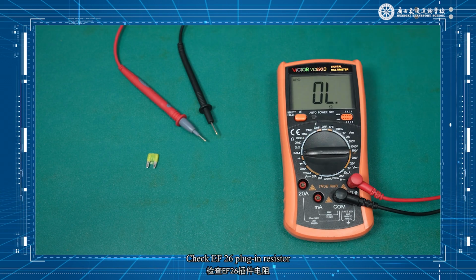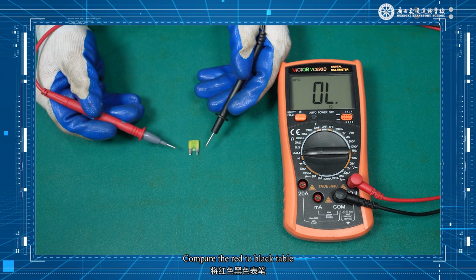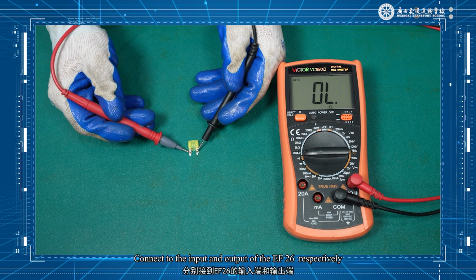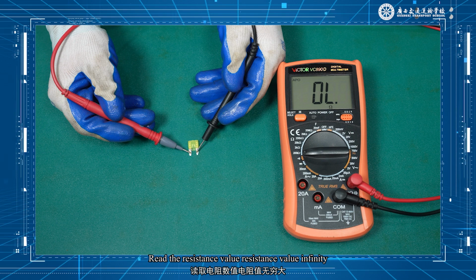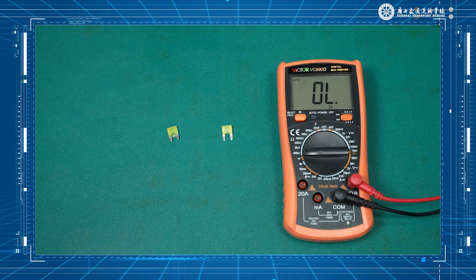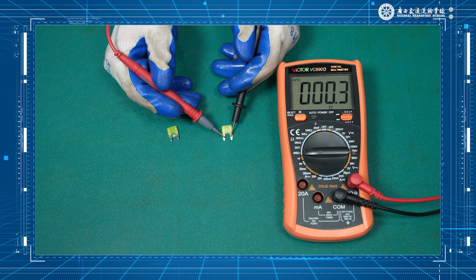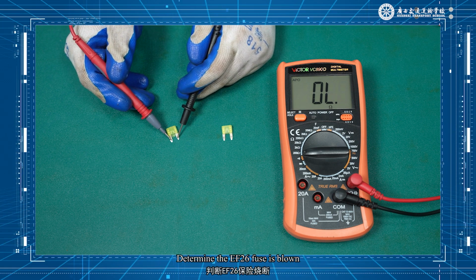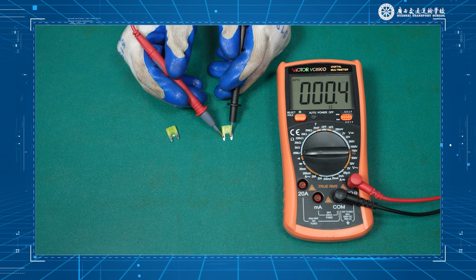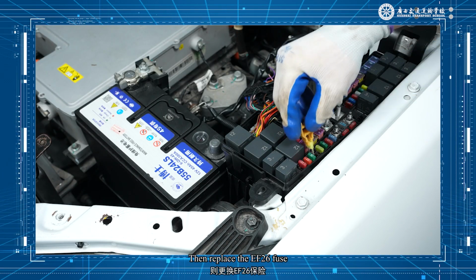Check the EF26 fuse resistance. Connect the red and black pins to the input and output of the EF26 respectively. Read the resistance value. Normally it should be less than 1 ohm. If it reads infinity, determine that the EF26 fuse is blown. If the above tests are normal, then replace the EF26 fuse.